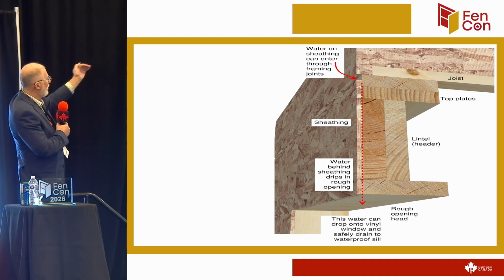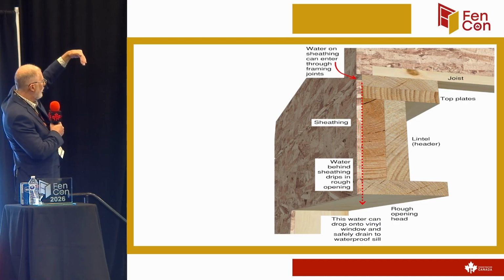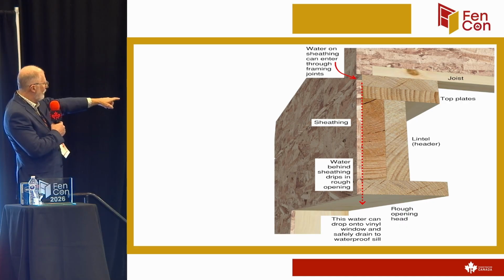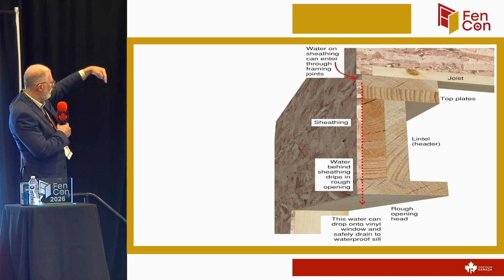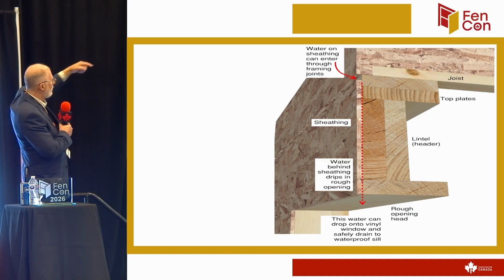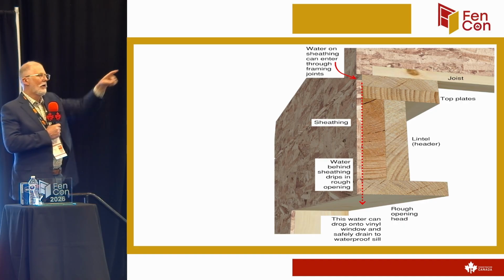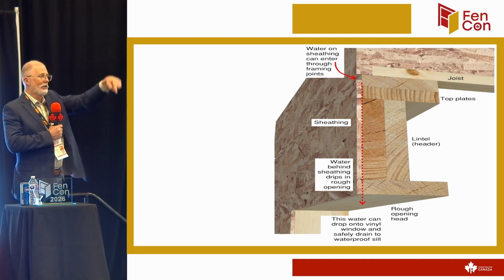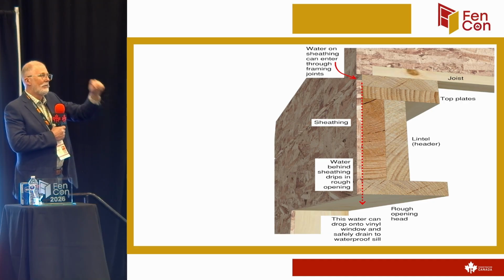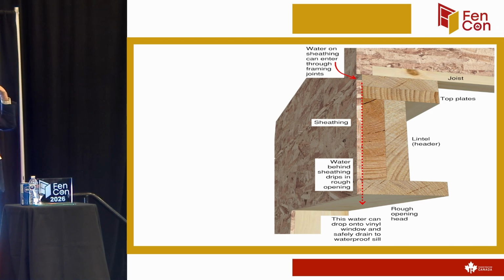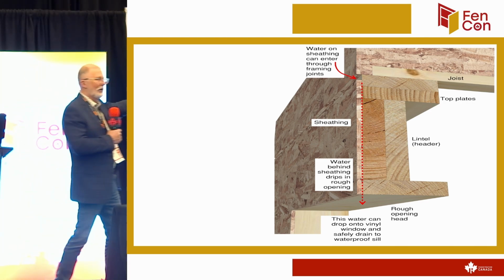It gets to that point. Now it's inside the sheathing and it's running downwards. See where the arrow's showing? It could run down in between the sheathing and come in, but it also could hit the 2x10s and come in the 2x10 and run all the way inside and down. You're absolutely right. But the risk, from my experience, is lower than where we're saying to do it.